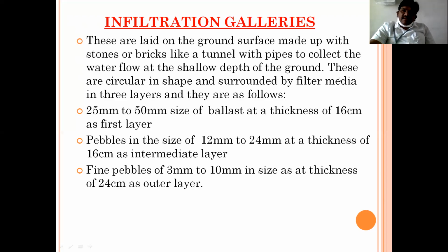Because the groundwater flow is maximum, by keeping these types of structures near those river banks, water automatically gets infiltrated into the ground, and as we have made weep holes in the galleries, water enters the galleries through the weep holes. Now we'll see how these galleries are constructed at the banks of rivers.